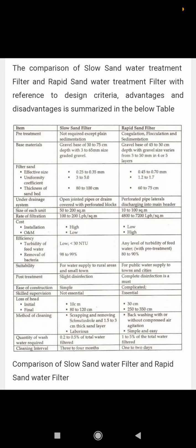That is the principle of aeration, the gas transfer, where when the water comes in contact with air, it releases the bad odor and gases from the water, and it adds atmospheric oxygen into the water. So that process is called the aeration process, where it removes the bad odor gases like CO2, CH4, H2S, and also it removes some of the bacteria present in the water. So this is about aeration.